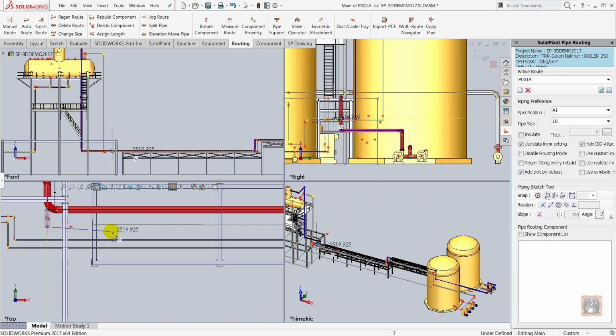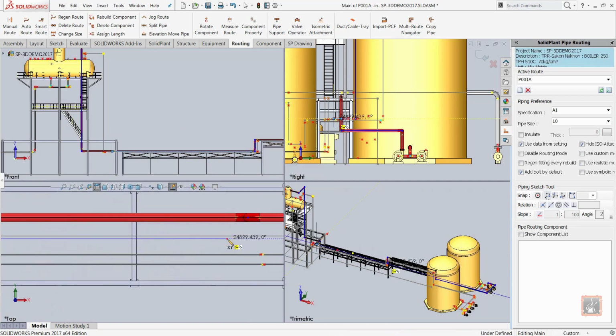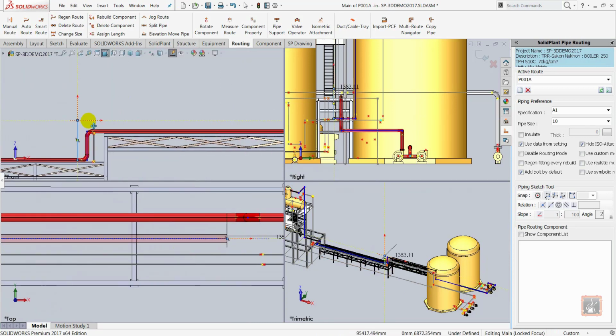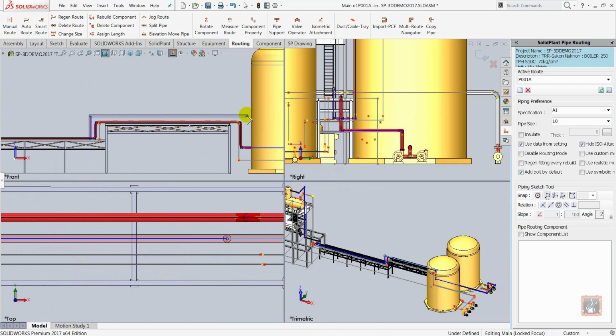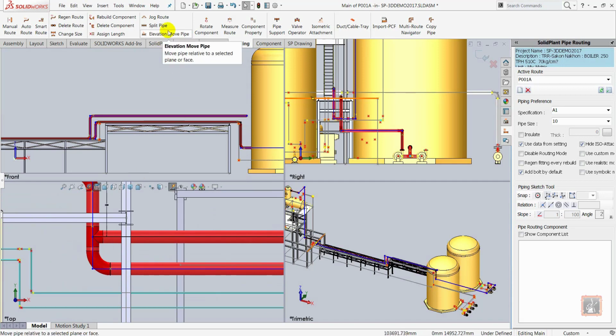One of the first things you'll notice is that I can just draw the sketch line from the existing 3D model. It's that flexible. I can switch between views just by dragging the line to the next window. You see here that the elbow from the existing line has already turned into a T. No need to do that myself.